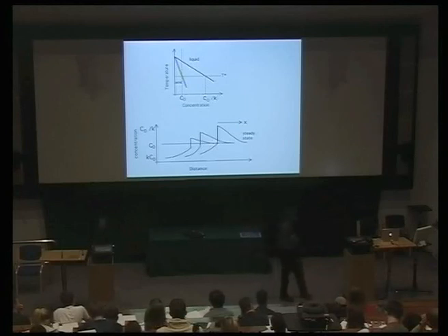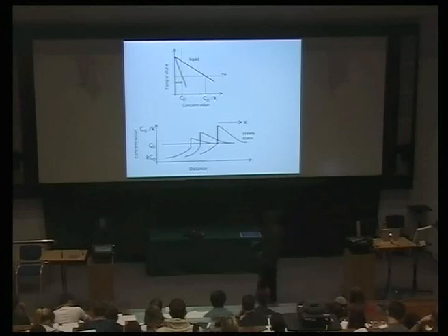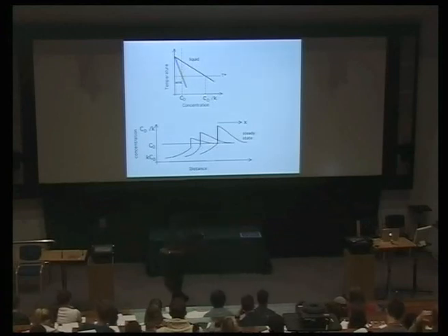And we've also made the assumption that there is equilibrium at the solid-liquid interface. We've said that the compositions at the solid-liquid interface here and here are given by a tie line of the phase diagram. There are many solidification processes where we force solidification to happen rapidly, and then that will no longer be the case. So we have to deal with non-equilibrium solidification as well.